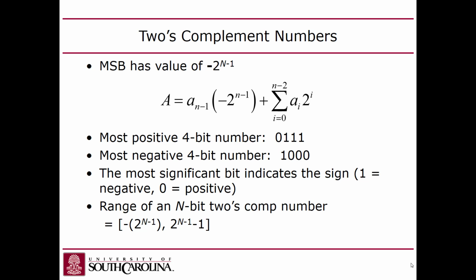Oh, with a carry. Kind of strange, but it's OK, because that carry goes away. It doesn't show up in the result because the result's only big enough to hold 4 bits. So result's 0. So negative 5 plus 5 is 0. There's an extra carry in there, but that's to be expected. In fact, you better get a carry if you ever do these. When you add a negative number, you're expecting that carry there. If you don't get a carry, something bad is happening.